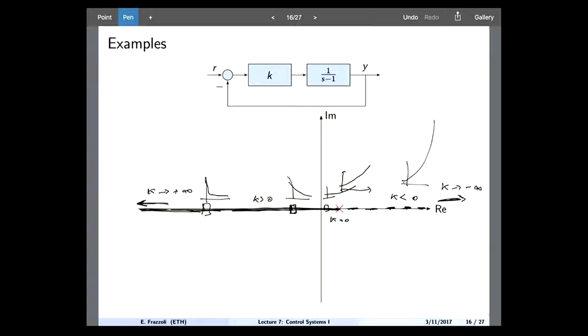Do you get the sense of what we are trying to do here? We will do more and more examples. What we are trying to do is understand, from the knowledge of the open loop behavior, just this pole here, what will happen if I apply feedback for different values of the feedback gain, okay? And what we found in this particular case is that as I increase k, I can make the pole of my system become stable, and I can make it as fast as I want in the stable region. Okay? Other examples.